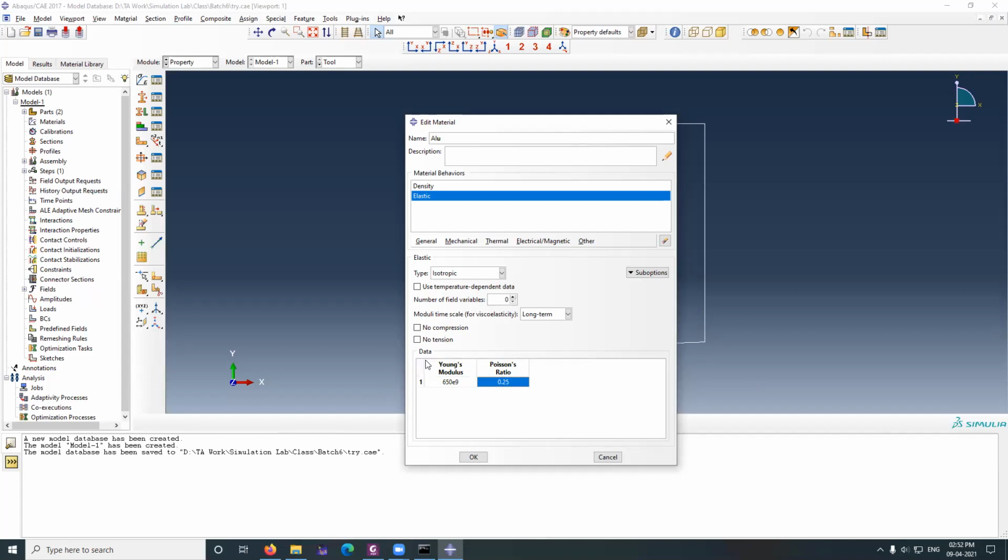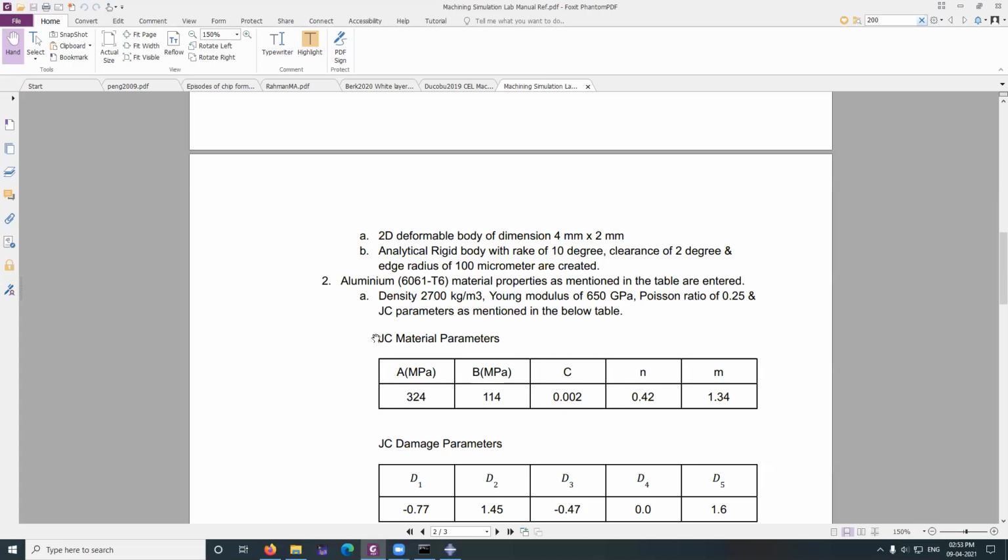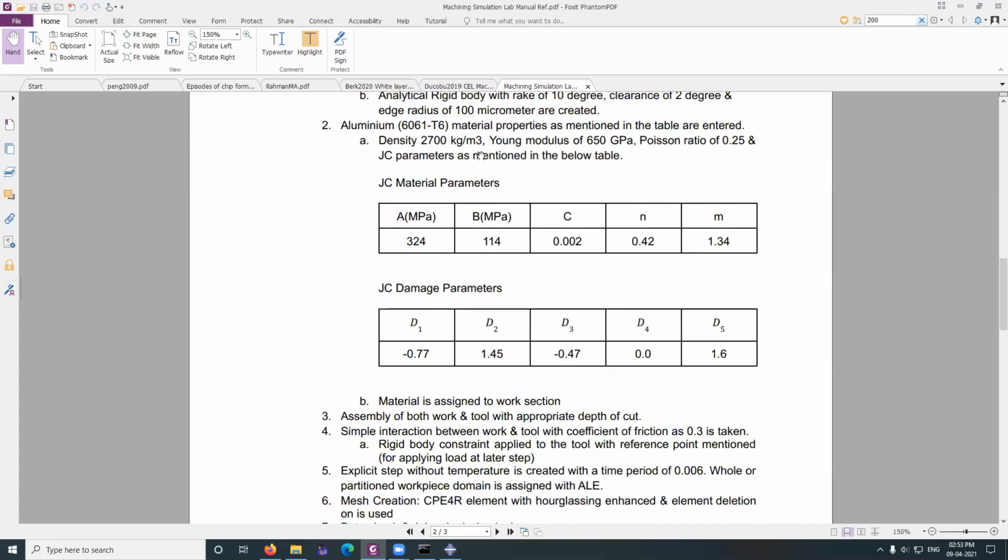At the start we have to know some guess of plastic strain, so that are yielding. So from this one, the computer will start guessing: what is the strain which we have to give it? We have to start with it like that. But the elastic part we have to give. That is very important. So Poisson ratio I give, and then only the plastic properties I have to give.